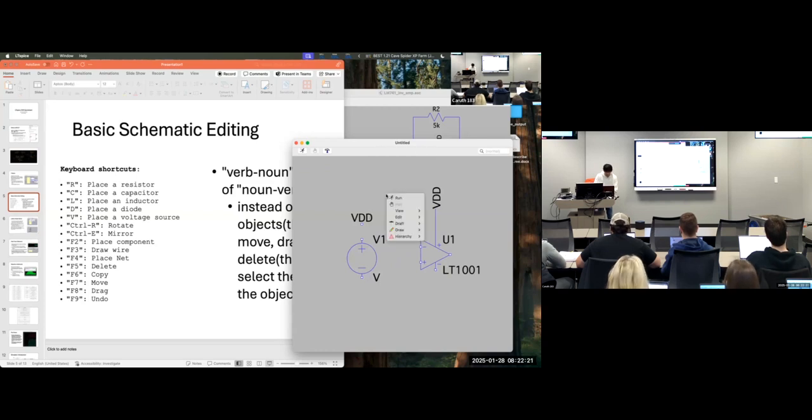And then I'm going to wire both VDD and the voltage source. I'm going to go to draft, wire. Boom. And just go here for now. And as you see, in order to fully place the wire, I clicked once and I can still freely move around. I don't want that. I just want the wire a little bit down the tail of the source. So I'm going to press escape, and then I should have the remainder of the wire here.